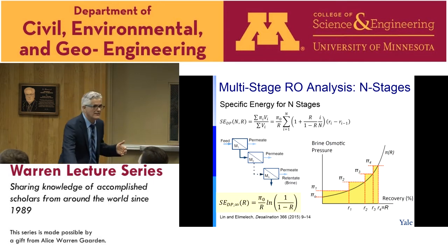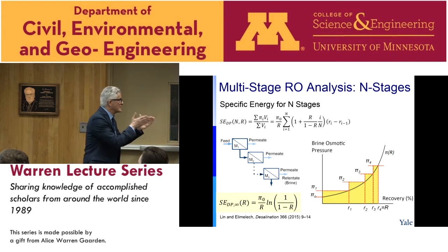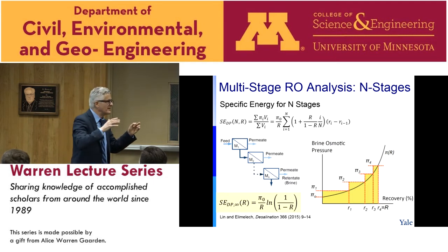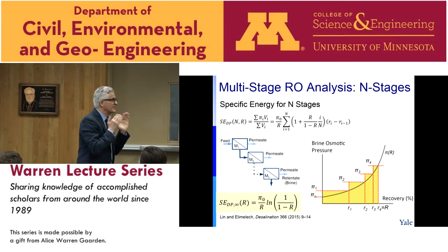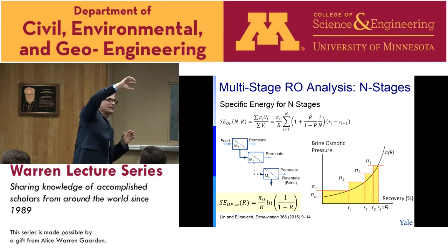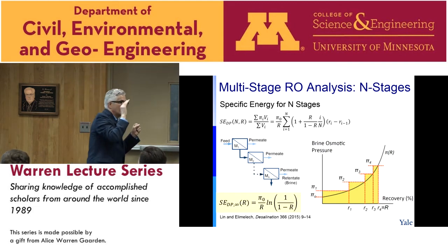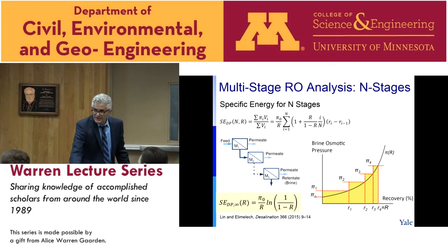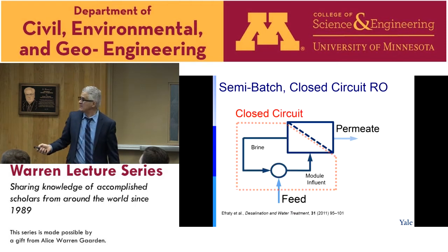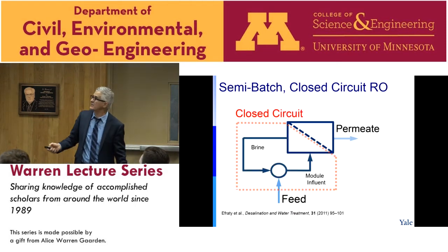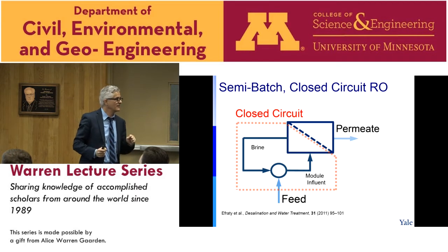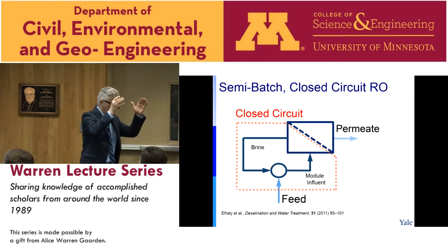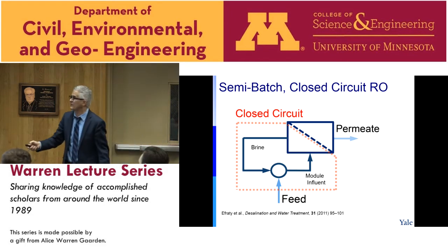So the question is, we have physical stages, and they increase the capital cost. Can we think about a different way, where you have operational stages rather than physical stages, and try to be close to the osmotic pressure curve? Because if you ride on the osmotic pressure curve, you will achieve the reversible minimum energy. There is a startup company in Israel that is doing very well now in brackish water desalination. They developed closed-circuit desalination. It has stages which are operational. You will have only 1 physical stage, but the stages are operational, and I'll explain.